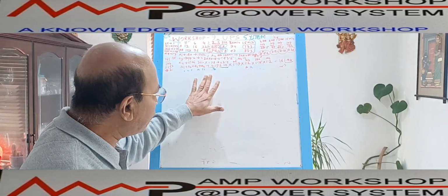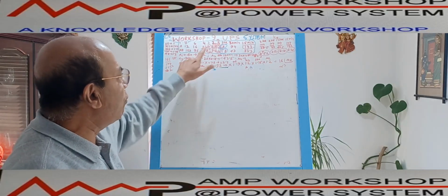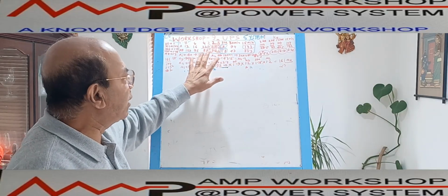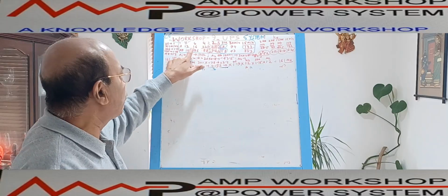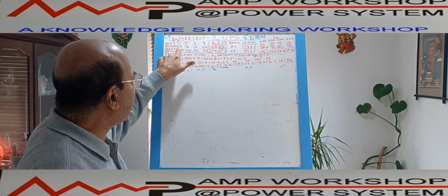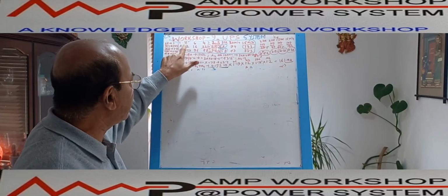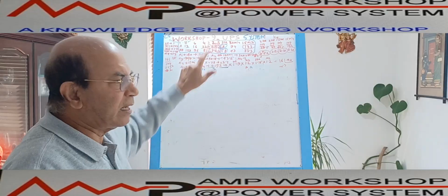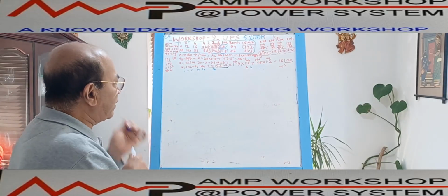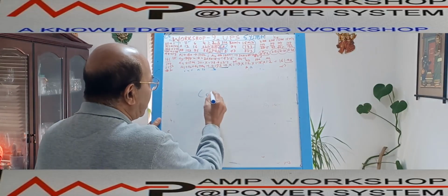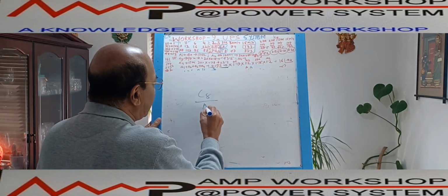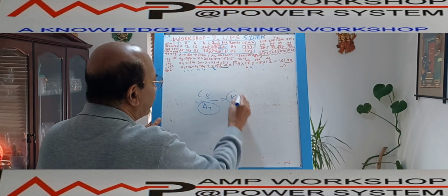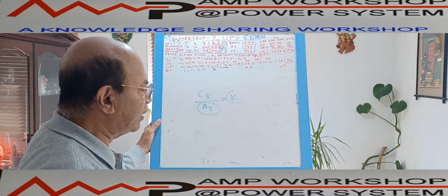Based on that timing, you have to see what the discharge current of the battery is for that time. If the total time is, suppose, 2 hours, then for the nominal capacity of the battery we are considering, what is the discharge current for that hour? The nominal capacity of the battery, C8 or C10 capacity, divided by that current will give the K factor for that section.